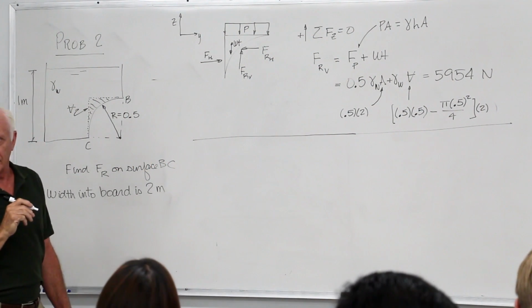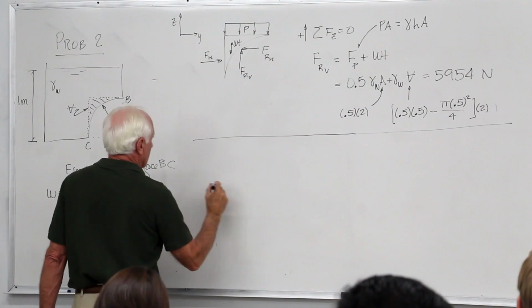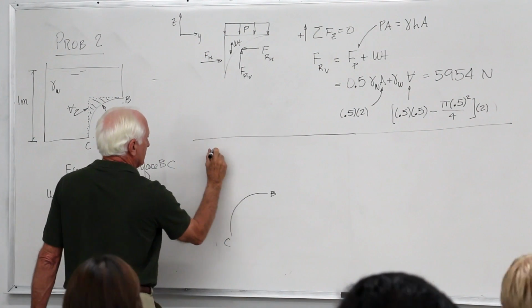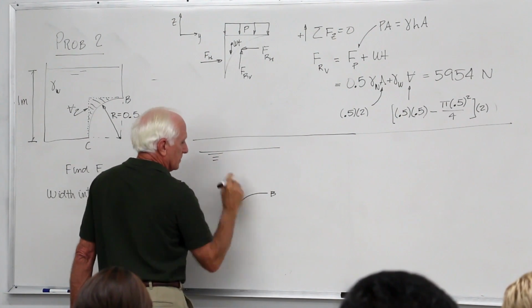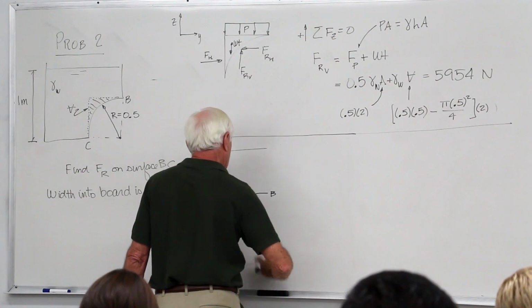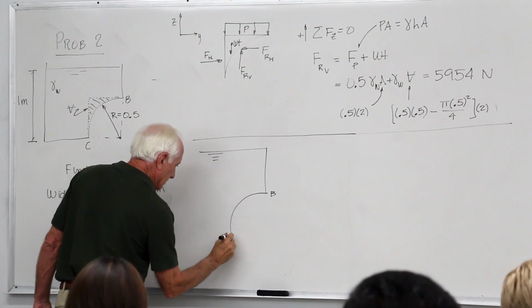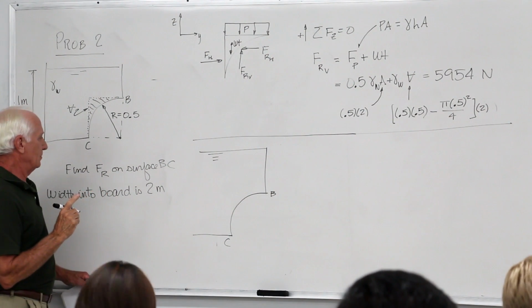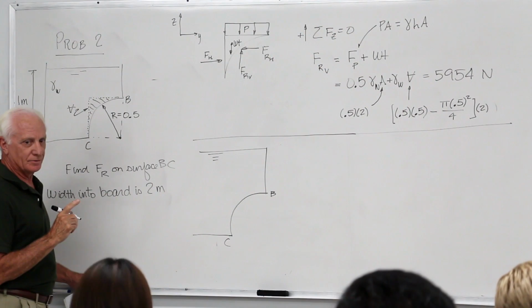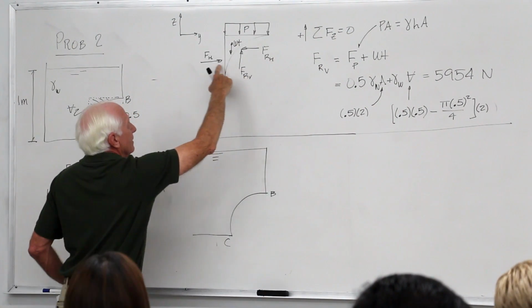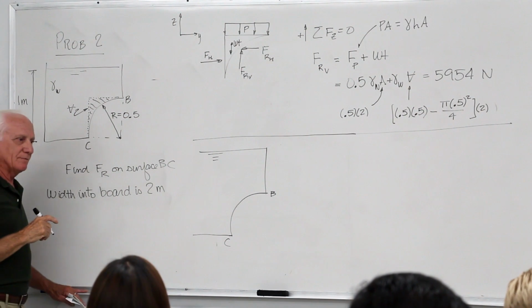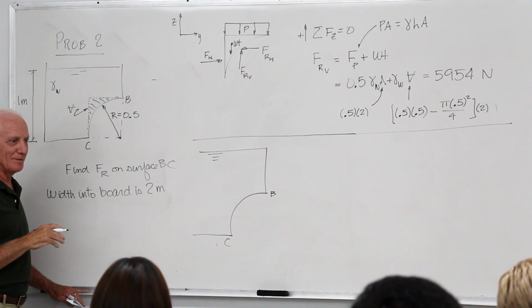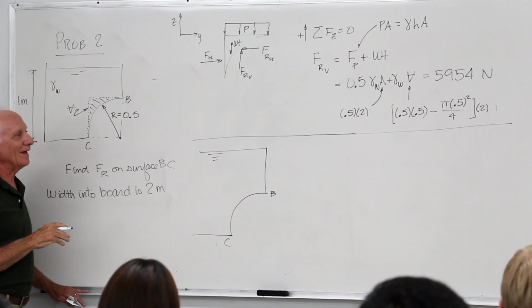Okay. Now we'll do it another way. Here's the same picture. Now I take force, now I take curved surface BC. Free surface. And I say, by the way, all I'm doing is finding the vertical force because the horizontal one is too simple. The horizontal one is F_H = gamma H sub C times A. That's the simple one. Very few people get that one wrong, unless there's a problem getting H sub C. So that one is a simplistic one.